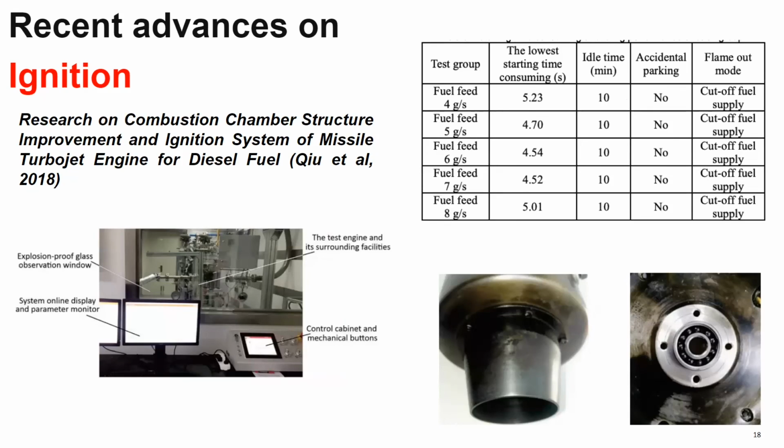The next one is a theoretical analysis that is accomplished by developing a mathematical representation of the combustion model and combustion conditions. The feasibility of using diesel as a small turbojet fuel is investigated using numerical simulation tools. The 3 primary areas of research are the improvement of the combustion chamber and evaporator, the selection of injector position, and the endurance of fire. A consistent temperature of 1200 degrees should be used for the igniter. The igniter needs to be properly preheated before starting the fuel pump.